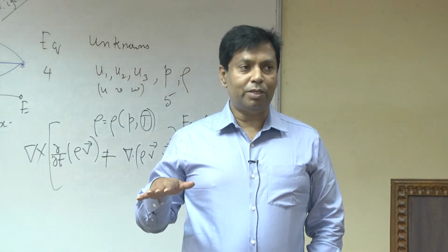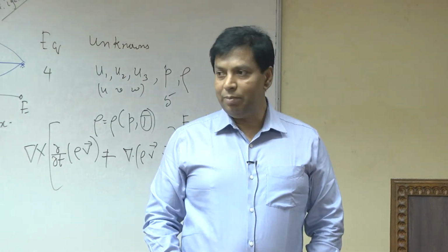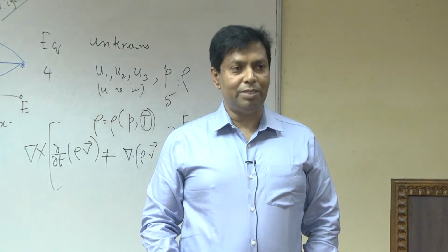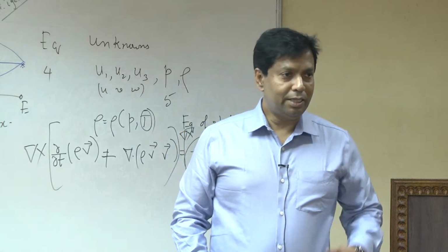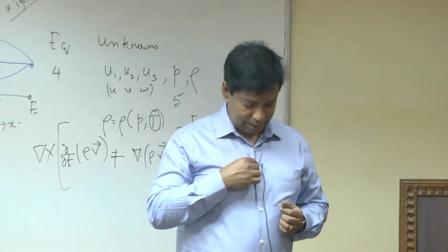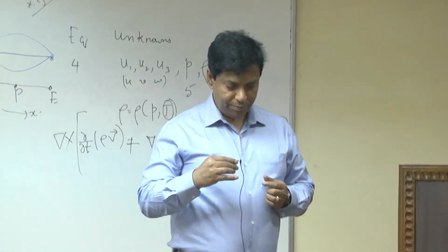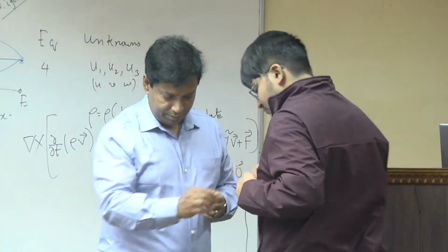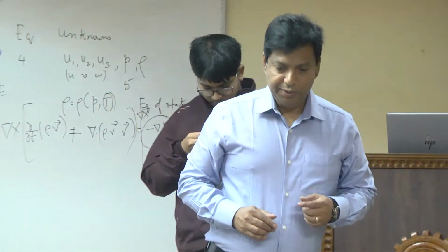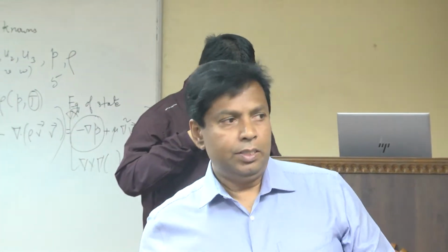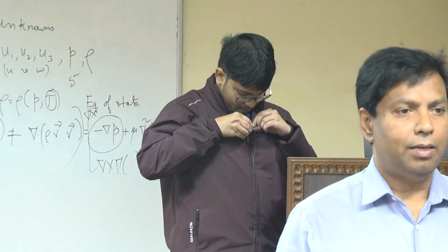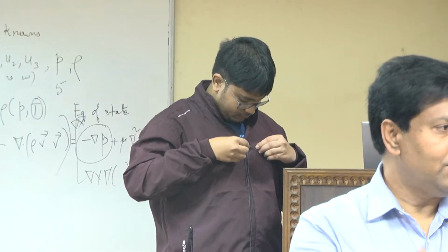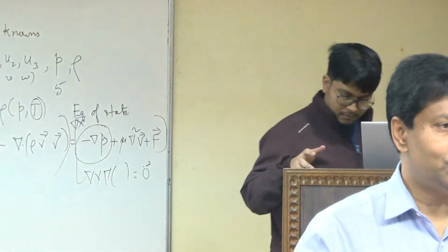So, this is only for demonstration purposes, but when you do the real simulation, you have to do the mesh dependence test. Okay. So, I think I should welcome him to start it. If you don't have Ansys on your laptop, or if you don't have a laptop, you can share with someone who already has it.